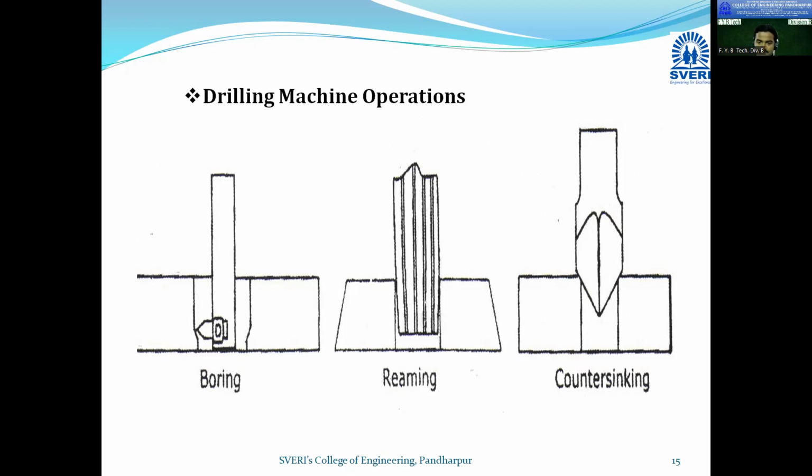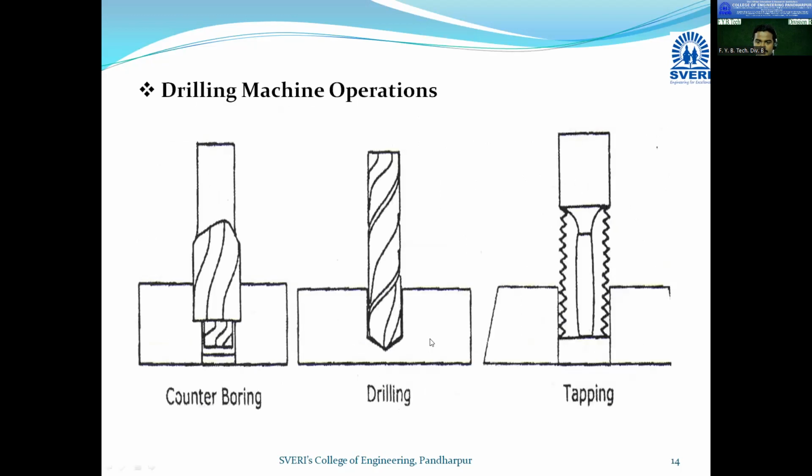Counter sinking. Okay, I think all the operations you have noted. One more is there, that is tapping. Tapping, T-A-P-P-I-N-G, tapping operation. So that is called as internal threading. So whatever the tapping is there, if you want to go for the internal threading, you can do the tapping.